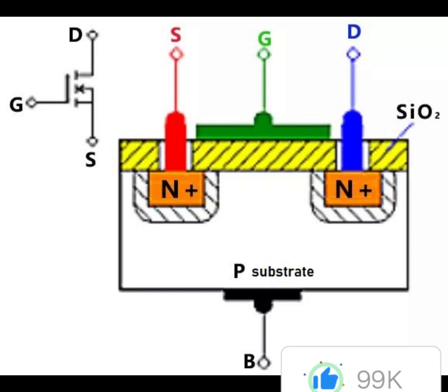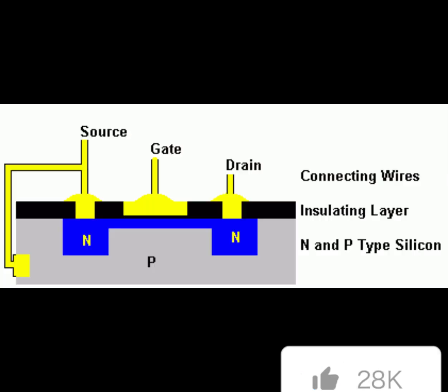The working principle of a MOSFET depends upon a MOS capacitor. The MOS capacitor is the main part of the MOSFET. Semiconductor surface at the oxide layer. It's located between the source and the drain terminals. It can be inverted from P-type to N-type by applying positive or negative gate voltages.